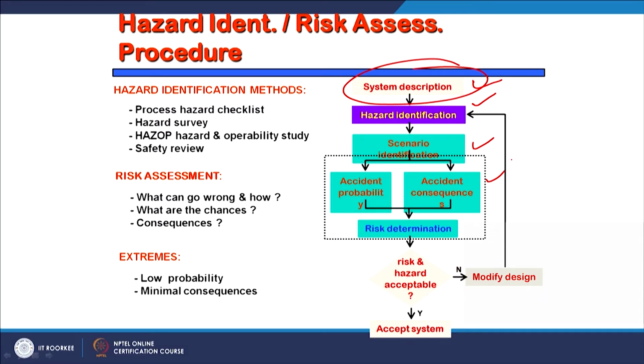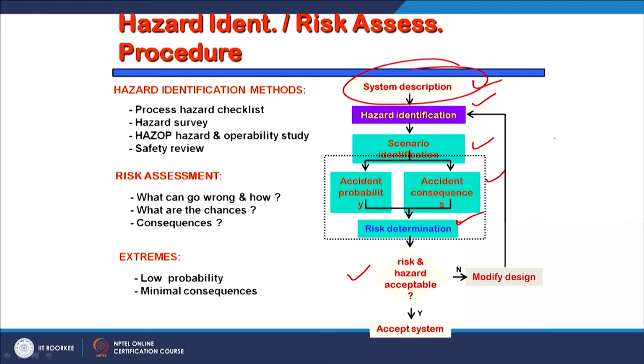Entire 15 kilograms of LPG exposed to the atmosphere. It may catch fire or it may not. If it catches fire, then what is the impact? What is the enthalpy? How can it impact the atmosphere? So based on this particular analysis, you need to determine the risk. Now, if this risk is acceptable, go ahead with the process, and if it is not, then again you need to relook at the entire study.